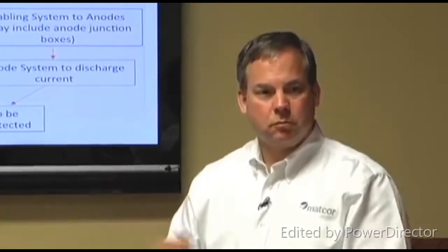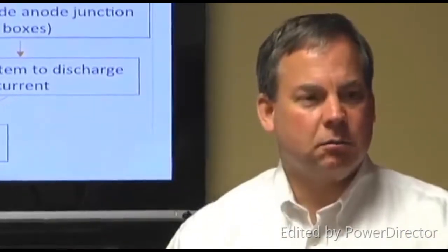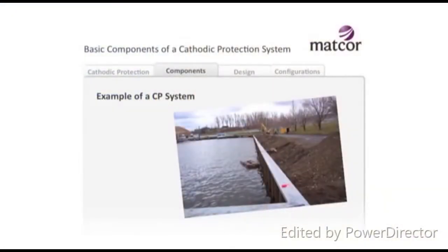So the rectifier is the power generator. And in some cases, there is no rectifier. I'll talk about that in a few minutes, about galvanic systems, where we actually are using a system that doesn't need a power supply. But in many cases, a power supply is needed, especially for larger structures or structures that you want to have a longer life on them. So let's just go through a quick example of a cathodic protection system, a real world actual application.